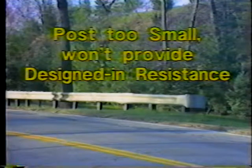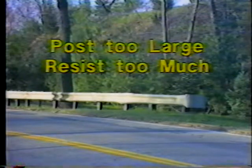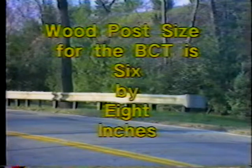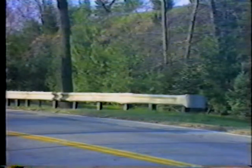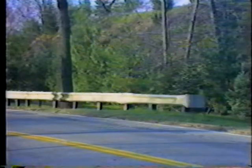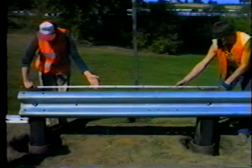If posts are too small, they won't provide the designed-in resistance when hit. If they're too large, they'll resist too much. Approved wood post size for the BCT is 6 by 8 inches. Normally, a Douglas fir post is used. Steel post measurements are 6 by 8 1/2 inches. Posts are set on 6-foot 3-inch centers.